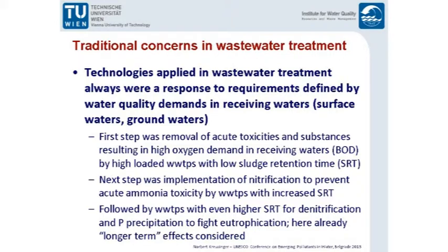And after that problem more or less was tackled, there was a new step. We found out that it's not only the oxygen consumption in the rivers, but that there are some substances like ammonia that directly lead to toxicity for fish, for example. So again, the reaction in wastewater treatment technology was to find solutions for that, and that led to the implementation of the nitrification step in wastewater treatment plants. Just a very similar approach as the previous one, but with an increased sludge retention time to allow slower growing bacteria to adapt to the wastewater and remove not only the ammonia but other substances too.